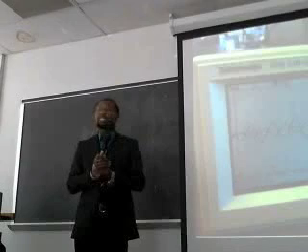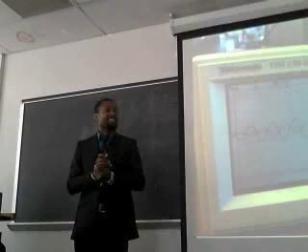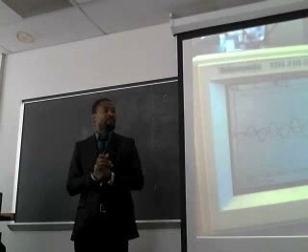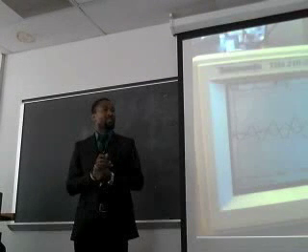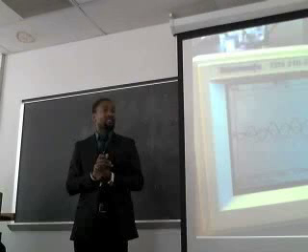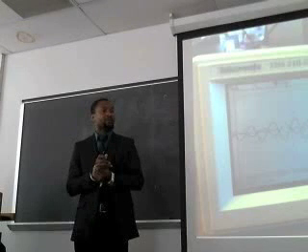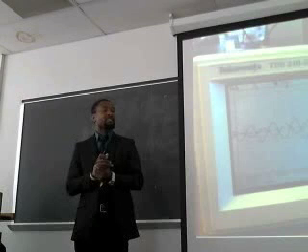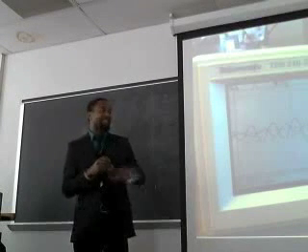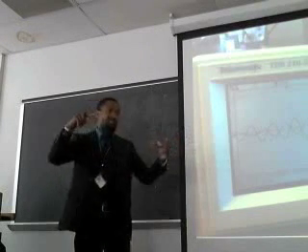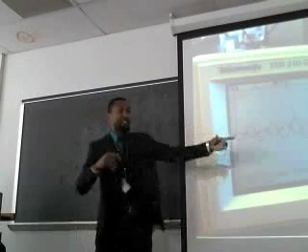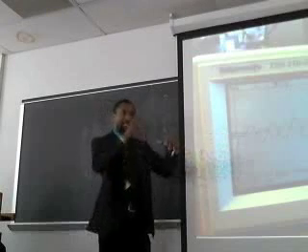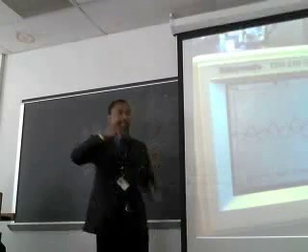I think what you have here is that the second phase should really have the same magnitude as the first phase, which it does not. And also the 120 degree phase shift is not there. So what you should do right now is look at the first phase standalone and the second phase standalone, and make sure why the second phase is not going all the way up. We did the same thing with the scope. We tried the first one, that's the first phase, then the second one. When you add both together, that's how it came up. But testing individually, we also get the wrong result.